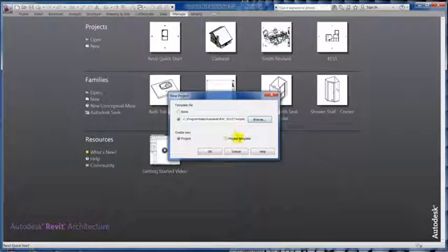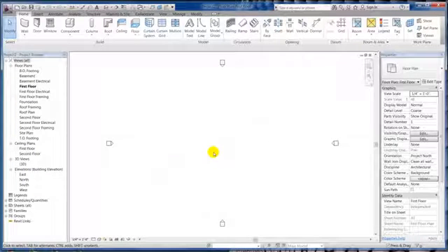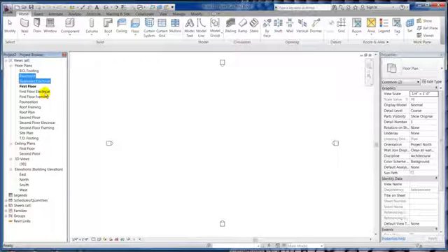Now there are certain levels in here that we're not going to use. It's going to be a very simple building. It automatically loads, you can see, with footings, basement electrical, finished floor, framing. If you want to, let's just go ahead and do this. We're not going to worry about a basement. Hold down the control bar, basement electrical. We're not going to do electrical.